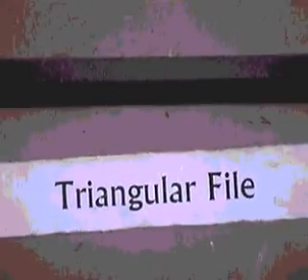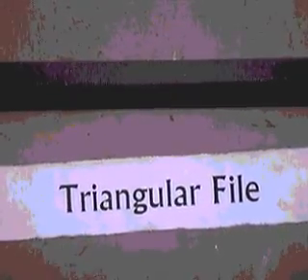Triangular file. Size is 6 inches. Material is again high carbon steel, hardened and tempered. It is used to make V slots and triangular holes.